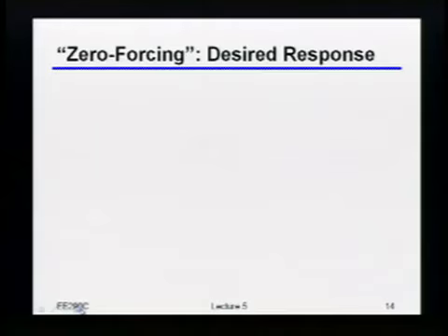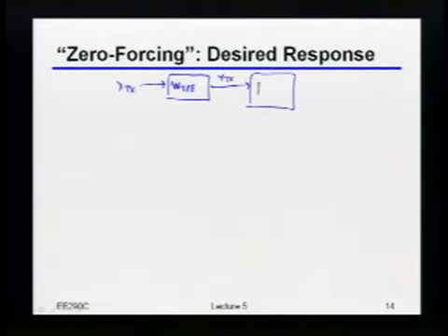So now that I have that formulation, we can start talking about how you would figure out the right value for the taps, or the coefficients. Okay? Just as a reminder, I'm going to redraw the block diagram over here, so that everybody remembers what we're dealing with. So we have our equalizer, which I called WZFE. That's the transmitted pulses coming out of that. Then we have our channel response. And finally, the received analog voltage.